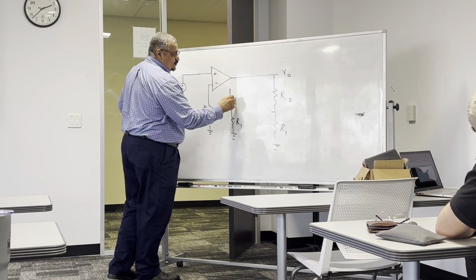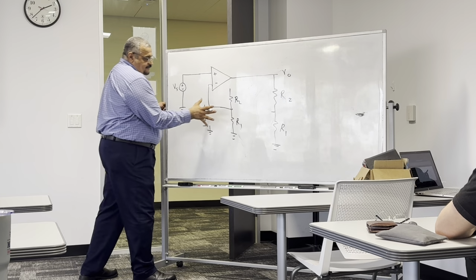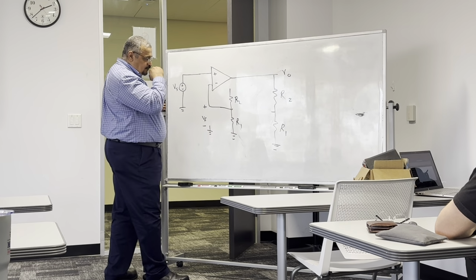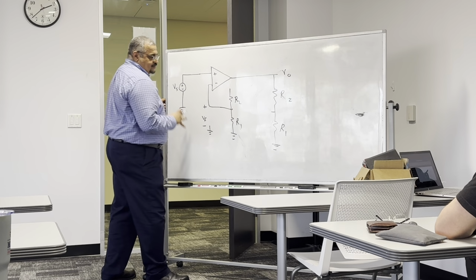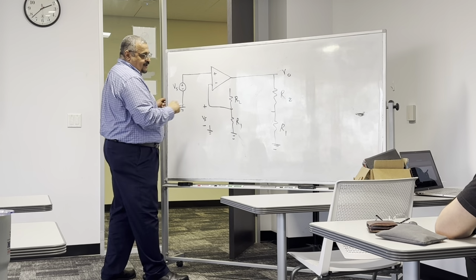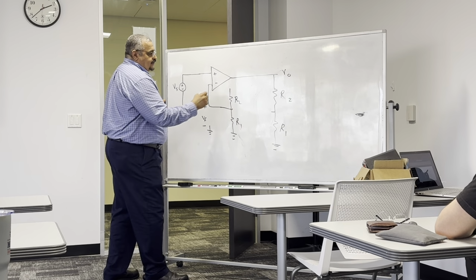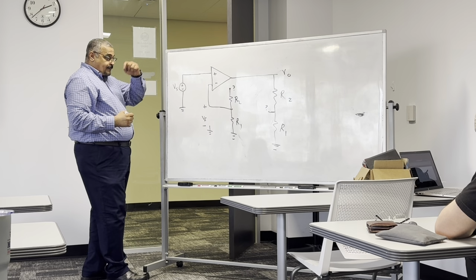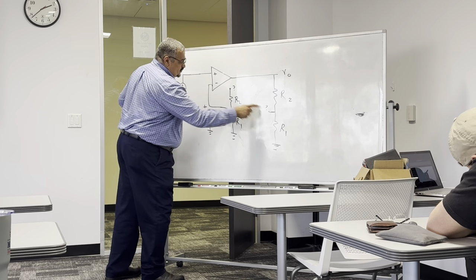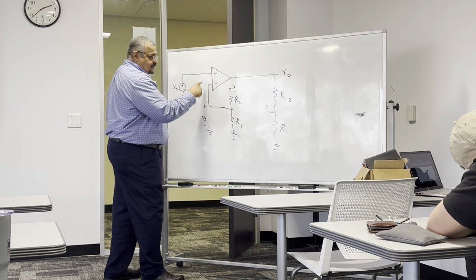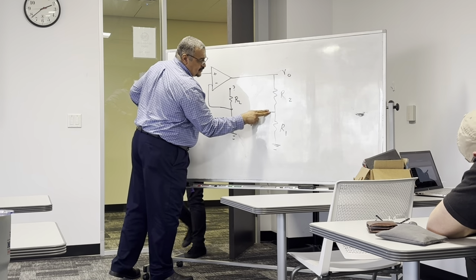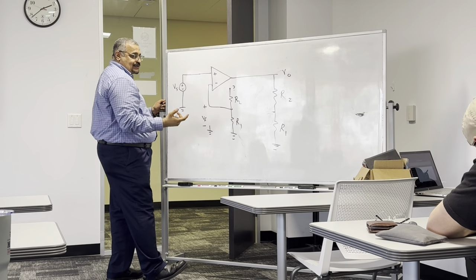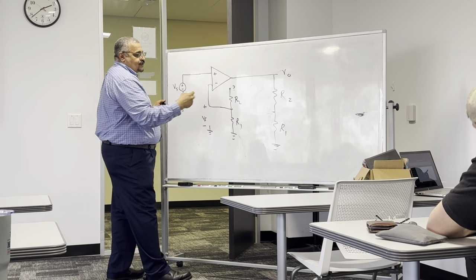One time at the input and one time at the output, because we need to keep the effect of feedback. If you remove it completely, then you don't have any effect of feedback, right? So we need to have a feed-forward amplifier without any feedback, but with the effect of feedback at the output and the input. Now, what should we do with this and what should we do with this? This is supposed to be here, which is mixing voltage in series. So leave it open. This was supposed to be here, which is sensing voltage in shunt, so then you have to short.